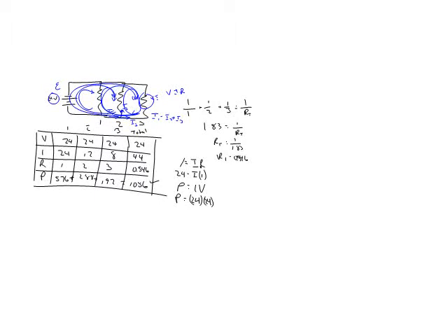What's tricky is, do you give it a positive or a negative? And I struggle with this too. That's probably the worst part of it. Is it positive or is it negative when I go around? The best way to do it is to assign a current direction to each thing. So when we go around in this picture up here, it said that the current is going down in each one of these. So it comes out of the battery, it's going down, it's going down, it's going down. I don't know if that's quite correct because you can see that the short end is on this side, and this one should actually be going up this direction. And this one should be going up that direction. So you should have currents going up and then around.